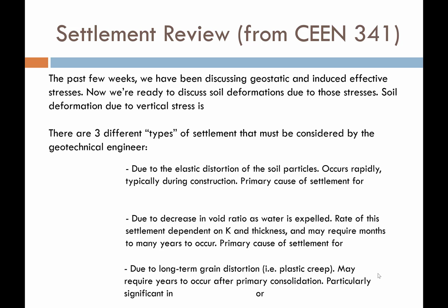If we think about the soil as lots of sublayers, think of it as lots of little springs stacked on top of one another. So if we can calculate the deformation in each little spring and sum them up over the whole depth of the soil profile, we can come up with an estimate of the total settlement that occurs in that soil.